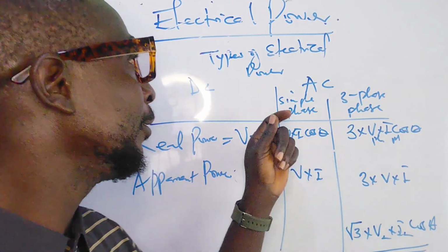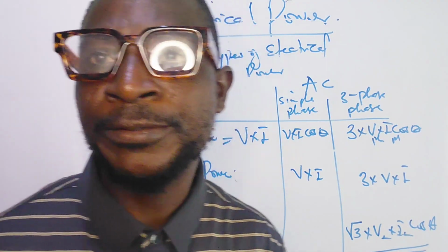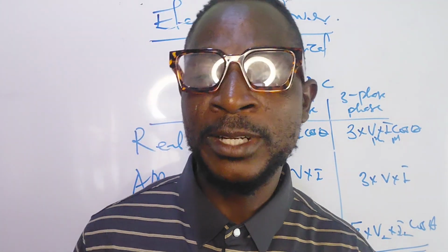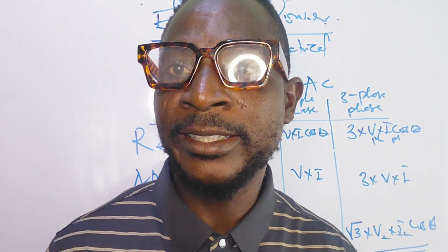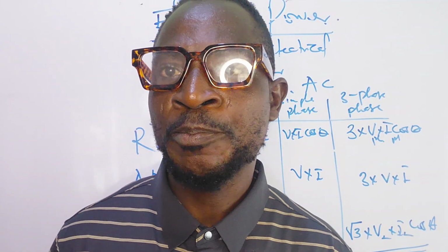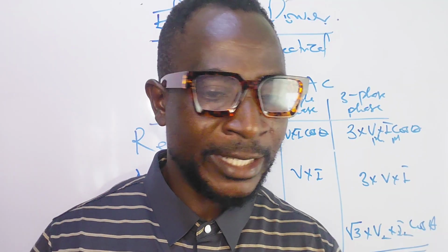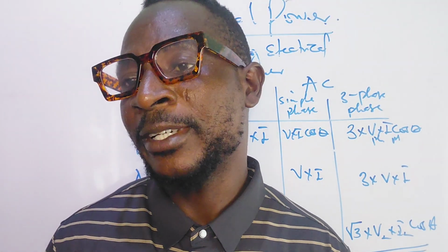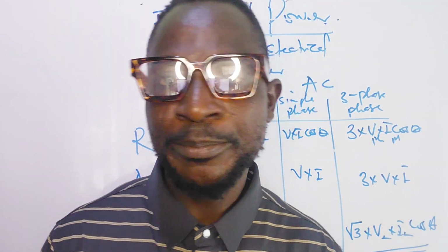So that is that. Please, you need to understand everything about this. If you have solar equipment and some are rated in kVA, kilovolt-amperes, what you need to do is convert it to the real power, let it be in kilowatts, because after your energy audit, you will multiply all your appliances, and most of them are rated in watts. So you have to get the real power.